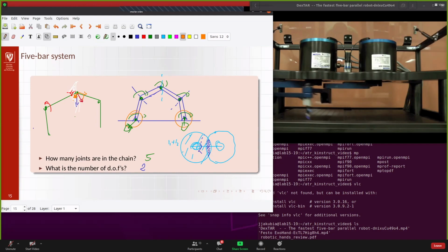Okay, maybe it's much smaller than the original red and the original blue. Some of this, so out of the blue force, part is compensated by the mechanical structure of the left arm, part by the right arm, and only a very small part really is applied to the arms as the bending force. So again, you don't need the dead thick arm. Of course, it is a simplification.